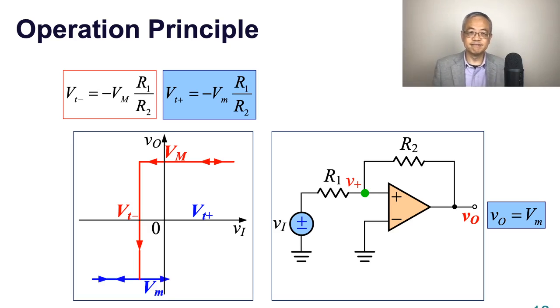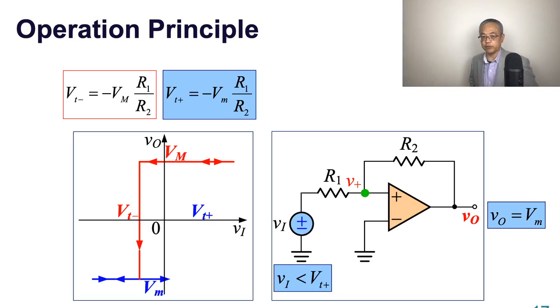Okay? So now we are located on the blue state. Then which one are you supposed to compare with? The blue one. When you change state, your previous focus on the red threshold voltage is forgotten, and you focus on the blue threshold voltage.